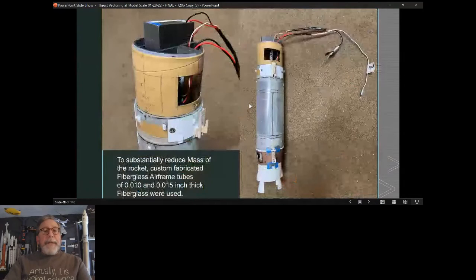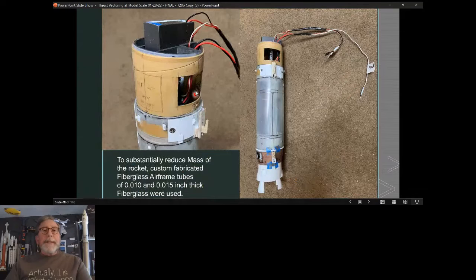And this is the avionics bay here. You can see in here the flight computer. It needs to have a hole in the side because it needs to get air in the side of the rocket for the barometric altimeter. So there were 4 little holes screwed into the side of the rocket in the final model.